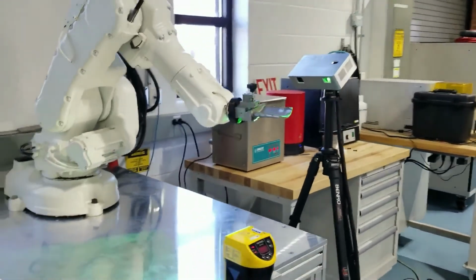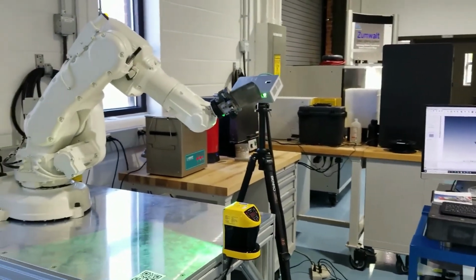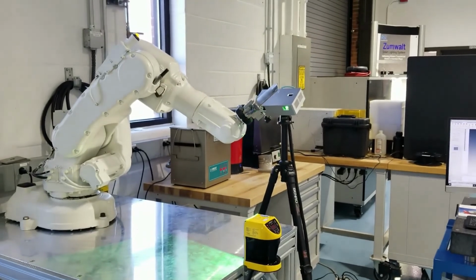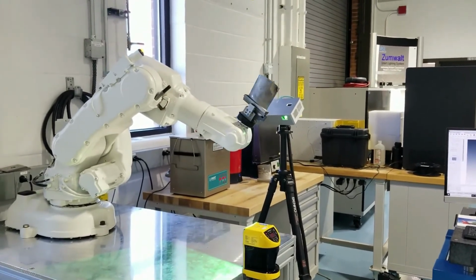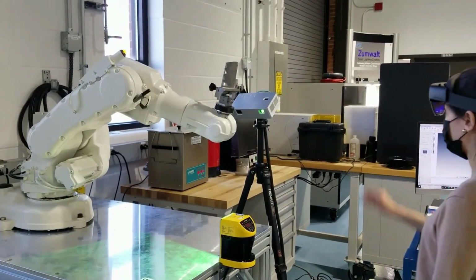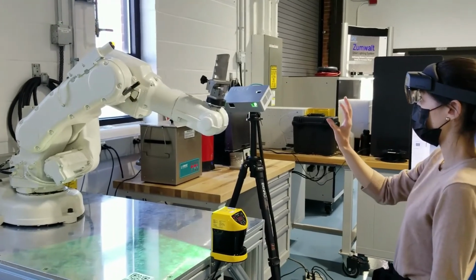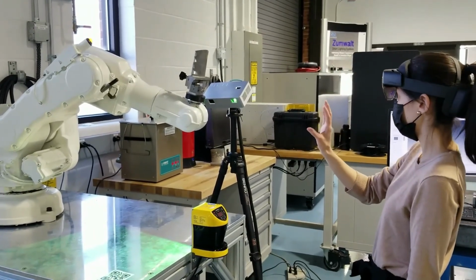So this airfoil shape has a specific pressure and suction side geometry. The leading and trailing edges are critical, and they have a specific radius. And the blade itself starts out with a thicker airfoil shape and thins down as you go to the tip.